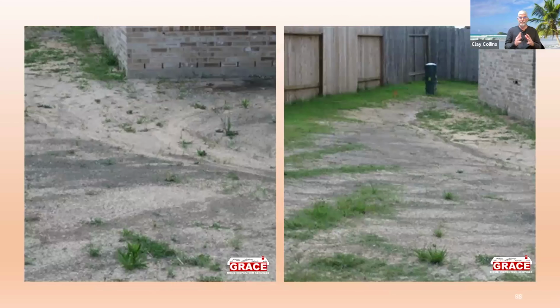All right. So new construction, and the homeowner says, I'm going to sod the back myself. But it doesn't take a few rains, even one heavy rain that hits that sand, that eliminates all of your drainage swale. Because remember, that type A drainage drains from the back fence and from the house, and it hits that, all the sand moves to the middle. The low spot is now eliminated. So I tell the homeowner in my report that they may have to regrade before they put the sod down if they don't put the sod down immediately.